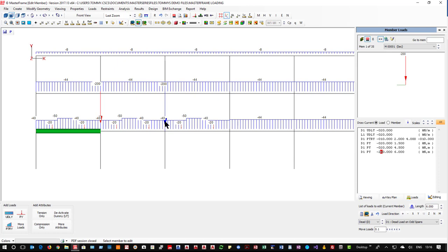Whereas this load, which is a nodal load, will go straight into the node and be dispersed between any members that can support it, such as the column and anything in here that's going to take it, but it's not. It's going to go straight into the column. So it's a great way of getting rid of that shear, but obviously the real answer is it is how you construct it. If the load comes in from a beam coming in a third dimension onto another beam, then you put it in as a beam load. If it's coming into the column, you would put it in as a nodal load. So if it's coming into the web of the column, put it in as a nodal load.